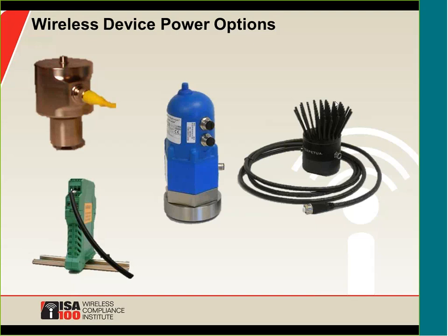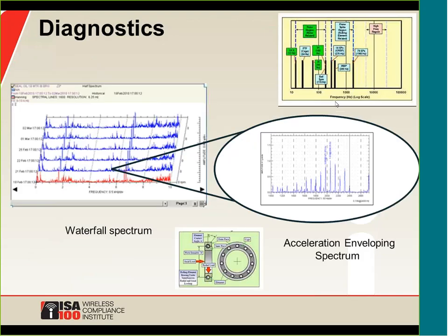And then one that's recently come about that looks very promising is a thermal energy harvester. And in installations, which are probably the vast majority of them, where there's a temperature differential between the air and the equipment that's being monitored of 20 degrees C or more, that thermal energy harvester provides enough energy to keep the wireless device running for the foreseeable future. So lots of options, lots of inexpensive options that further improve the value of wireless data collection.